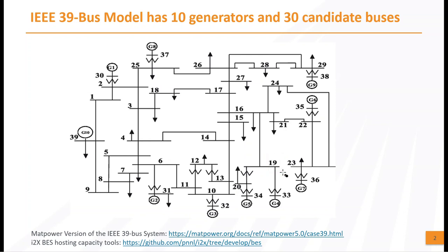So, ways around that: the system could be strengthened there. They may call for ERIS, the Energy Resource Interconnection Service. But anyway, for the purpose of this bootcamp example, that's how we came up with bus 14 and the 300 megawatt size. So it wasn't completely arbitrary. The load flows we did in MATPOWER for this. You, of course, will be using something else for production grade work.